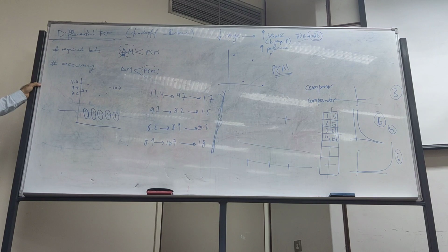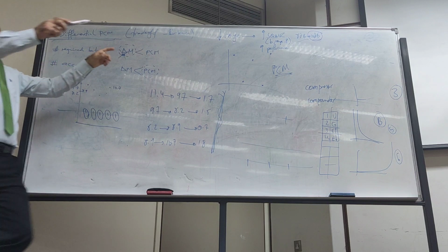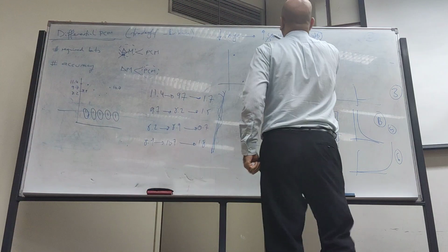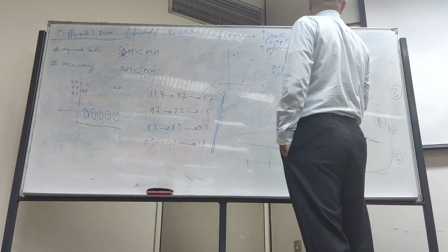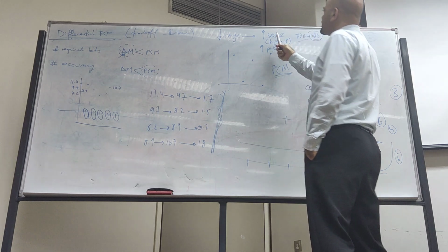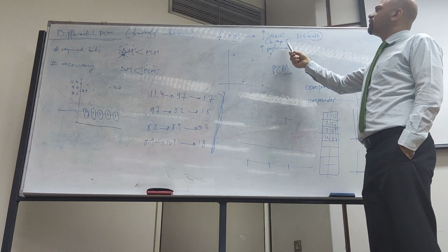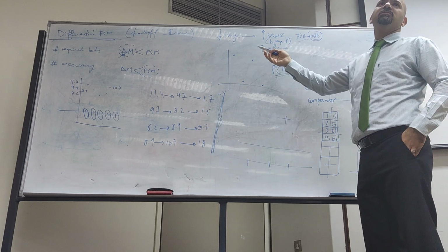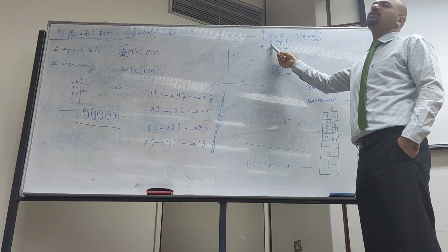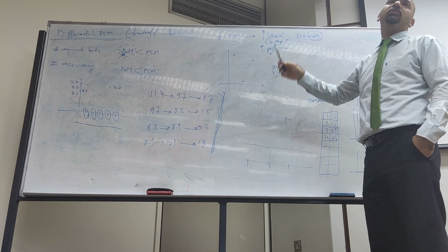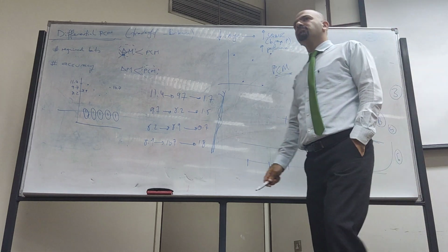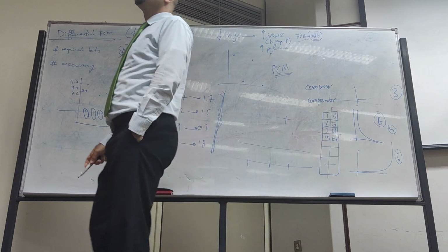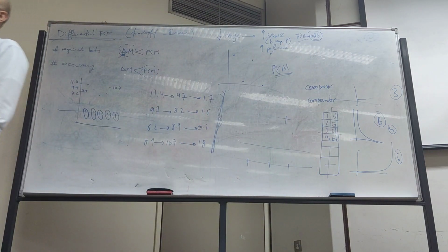Hussein, what's lost? Fewer bits. Where are fewer bits? The SQNR depends on the bits, on the range, and on the power. So if I improve the range here, I will pay this improvement to be better in terms of B or better in terms of power: fewer bits or less transmit power. Good so far?